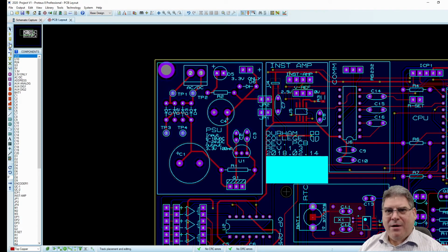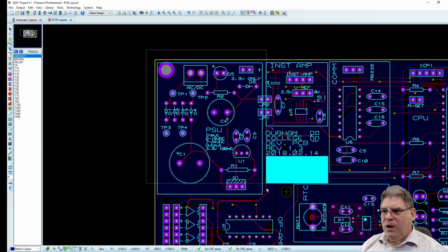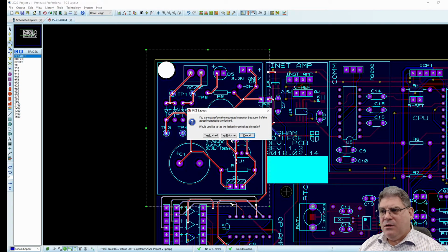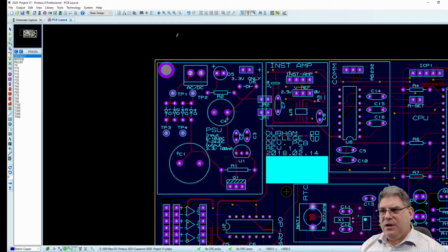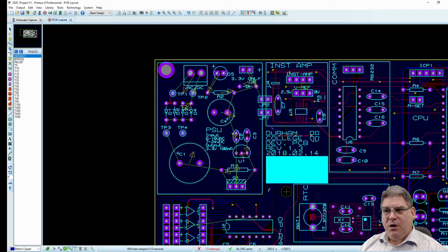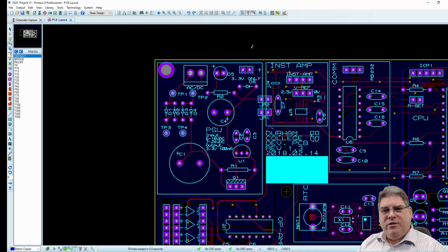I'm going to go into track mode, and then you'll notice that when I window stuff, only the tracks get selected. Then I can press delete to get rid of all of those tracks. Okay, boink, gone. The reason it was giving me trouble is because I locked this component, but we'll deal with that later. And of course, should you make a mistake, Control Z brings it back. Make sure that you save at some logical point so you can bring them back and forth.